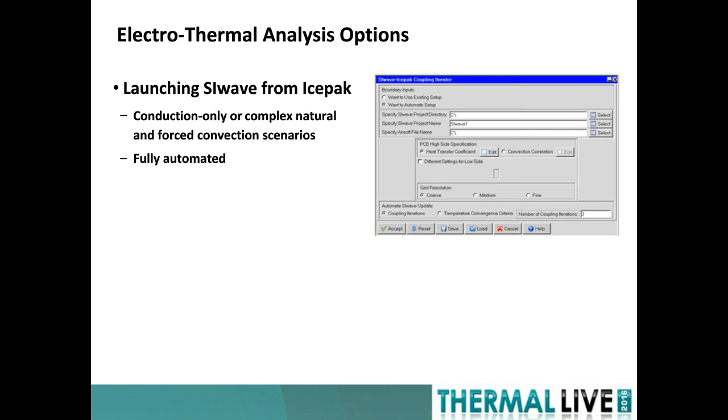Okay. So we have another question. How do you iterate with different values of convection coefficient, from low to high, and then figure out whether the conjugate heat transfer is important to include or ignore? Yeah, so if you want to look at different heat transfer coefficients and how they affect the solid phase temperature, you can do it parametrically.